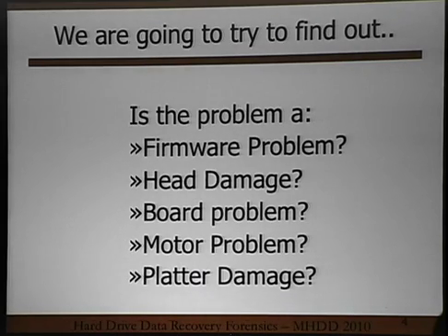All right, so anyway, this is the basics of what I'm trying to cover today. These are the 5 major issues that you have to deal with when you're dealing with a hard drive and you want to know what's wrong with it. A lot of people will go, I plugged in the hard drive, I don't get any user data. So what happened between there and not seeing my user data? That's what I'm focusing on here.